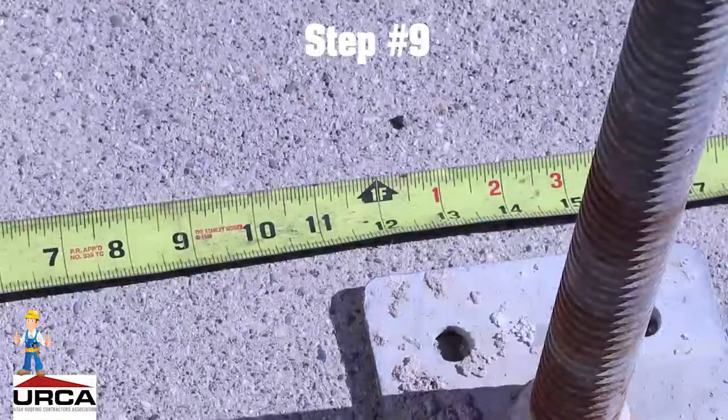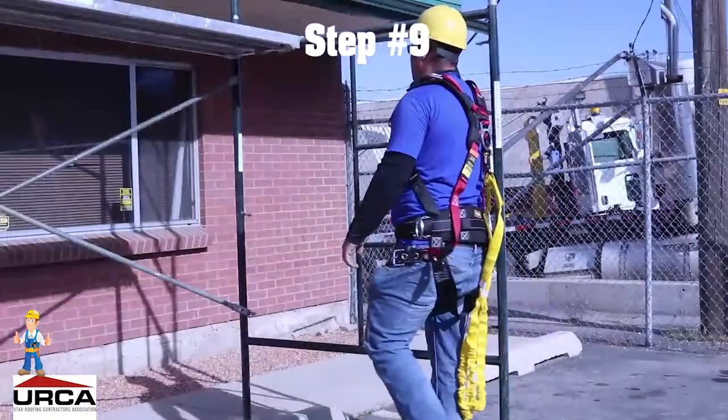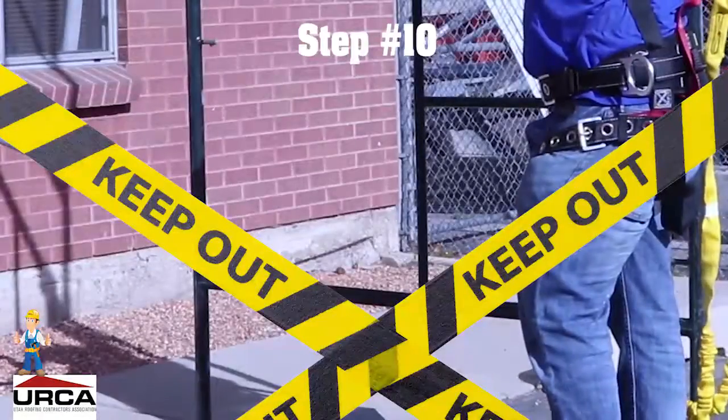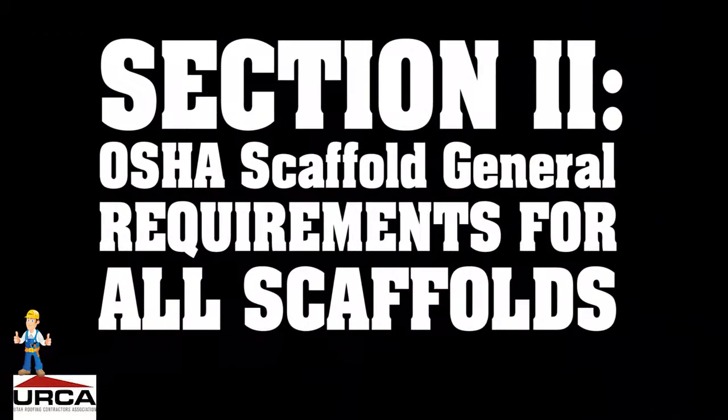Step number 9. Front edge of platform should not be more than 14 inches from the work unless using guardrails and/or a PFAS. Step number 10. Barricade area below a scaffold to forbid entry into that area.